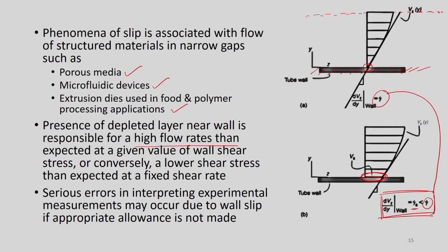the slip velocity. Because the working principles that we have developed for the capillary viscometer are for fully developed flow, but with the no-slip boundary condition at the wall. That is what we applied in the previous lecture, if you recapitulate. But that is not true here, so it is causing some additional velocity. This additional velocity has to be subtracted from the experimental velocity values, and then that V minus Vs has to be used in the nominal shear rate or true shear rate calculations. Okay.